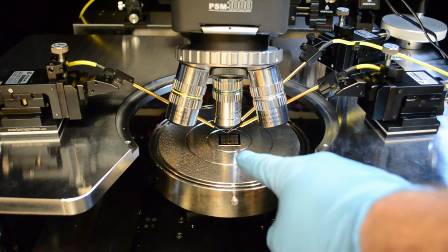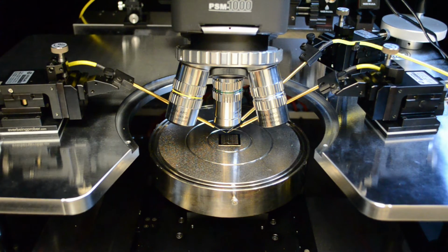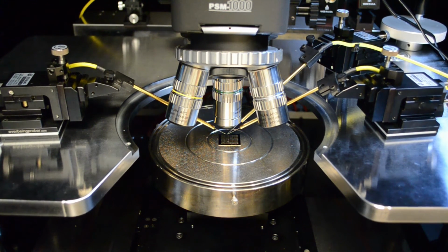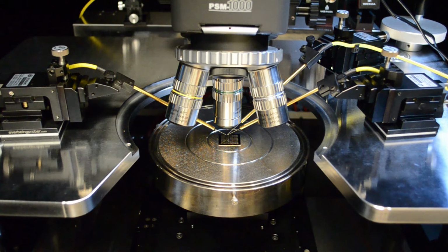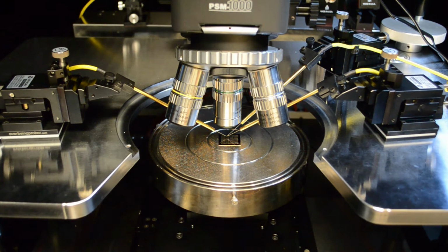At the bottom here is the piece of wafer with the fabricated devices on it. And you can see that the probes are located just above that. I've already aligned the probes by looking through the microscope just a moment ago, and what I'll do now is go ahead and lower the probes down using a lever that's on the edge. You'll notice here that the probes are coming down to the surface, and at a certain point they'll finally touch the surface of the device and make contact. It's at this point that I can begin testing.